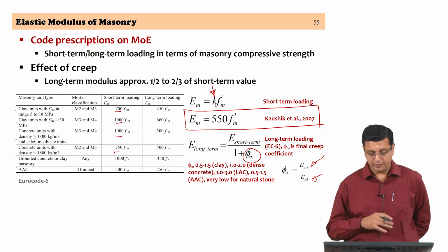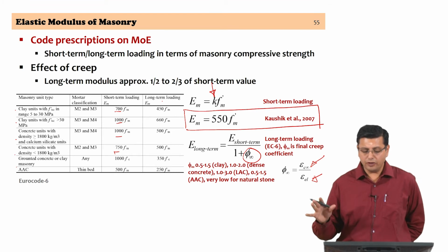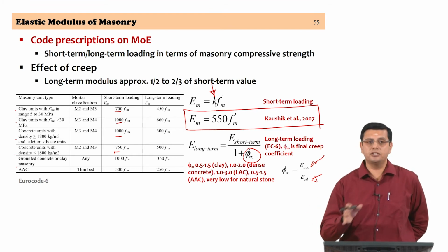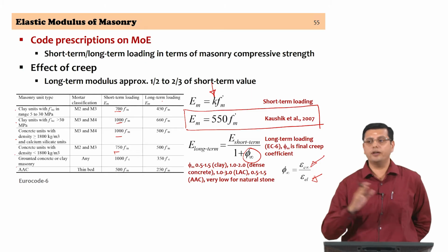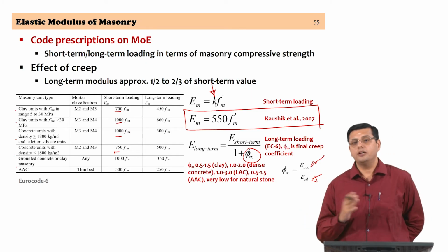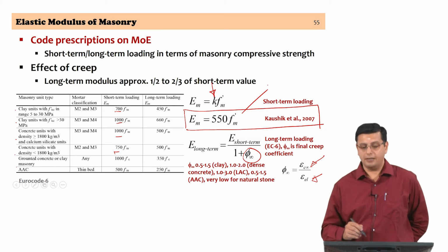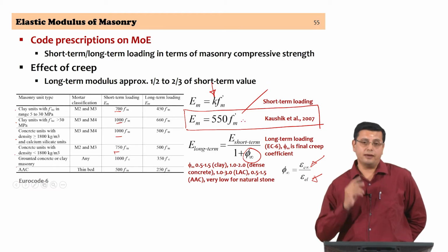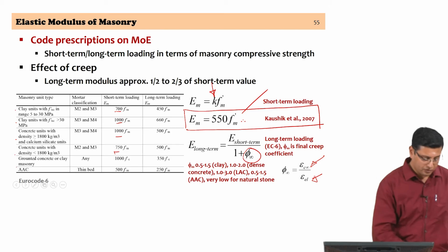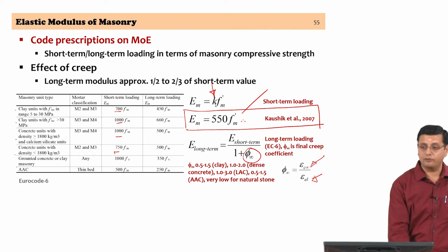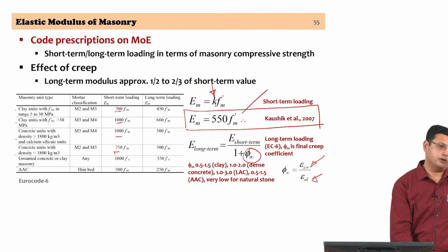So, word of caution on modulus of elasticity: be conscious whether you are looking at short term loading or long term loading. Values typically prescribed by codes would be for short term modulus, but if you were to account for long term effects, know that you will have to get the modulus of elasticity for long term loading itself.